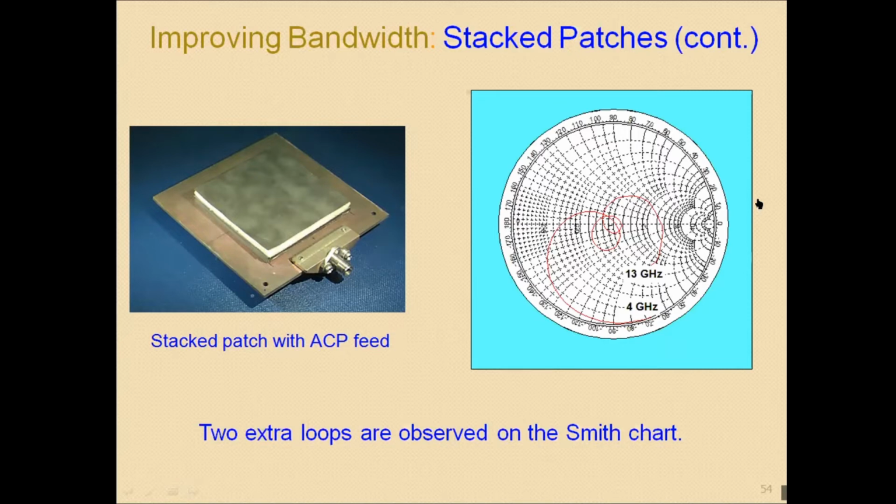When there is no reflection, the standing wave ratio is 1, right? Standing wave ratio varies from 1 to infinity. So the minimum standing wave ratio is 1, for reflection coefficient 0. When you draw the S11 curve on the Smith chart, you can test the impedance matching for the different frequencies and check what the standing wave ratio would be.